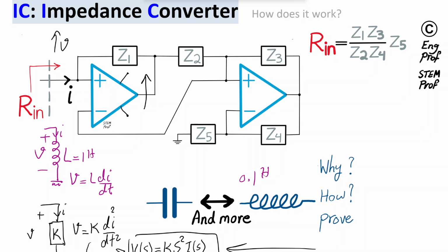Then that means via this connection, the input negative terminal is also moved up. So basically the negative terminal tries to catch up with the positive terminal, indicating that we have the proper connection in terms of negative feedback in the system. Another example is on this side as well. If we increase the voltage at the positive terminal suddenly, then the op-amp notices that the positive terminal voltage is increasing, and then it would increase the output voltage to max, which is close to V supply.